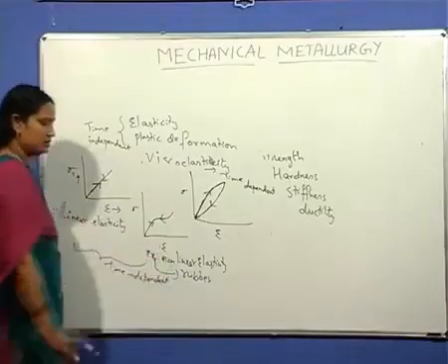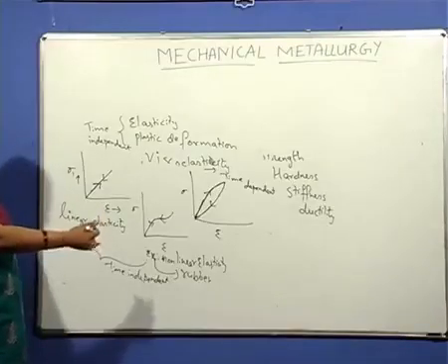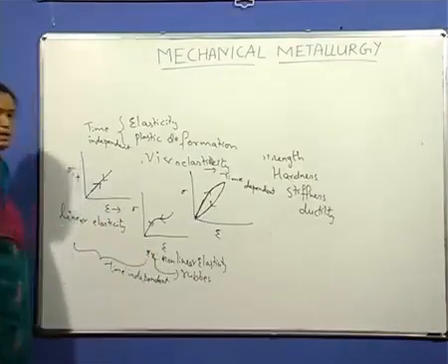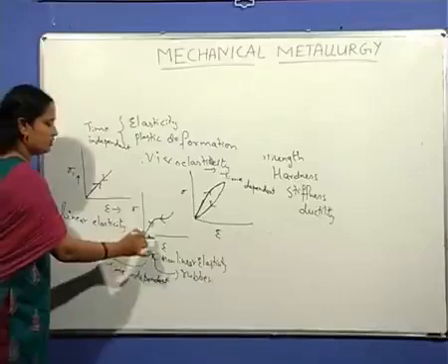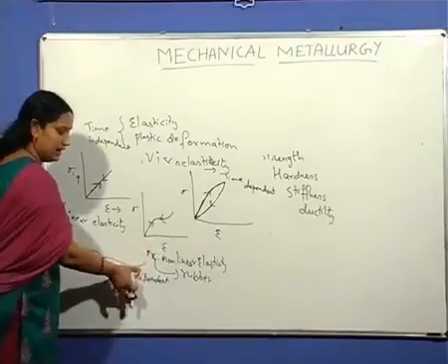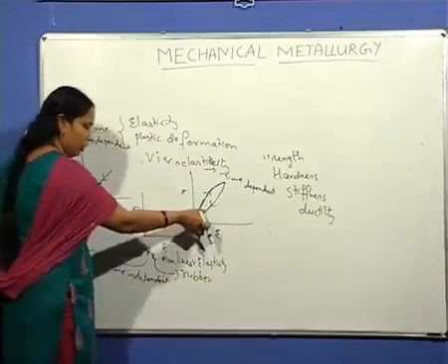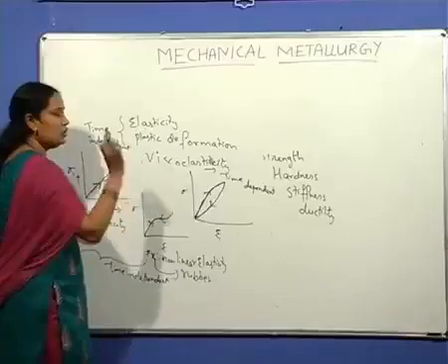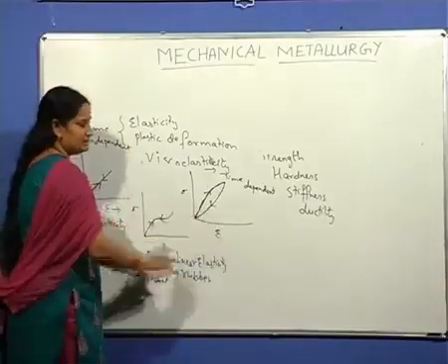Non-linear elasticity is also time independent. Some materials which show this type of behavior are elastomers, for example, rubber. The stress strain curve is non-linear, but it is time independent. A similar example of non-linear elasticity is viscoelasticity. This is time dependent elasticity.